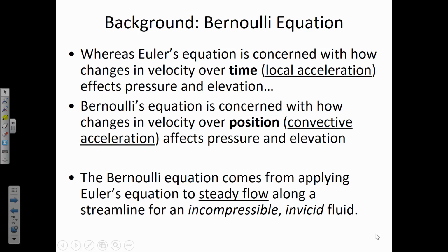Now, some fluids have a low viscosity, like gases, for instance, have a relatively low viscosity. Liquids, their viscosity is higher. So it's kind of interesting that when we've got a fluid that satisfies the incompressible assumption, like a liquid, water is relatively incompressible, but it's bad at being inviscid. But then gases are good at being inviscid since they have a relatively low viscosity, but they sort of fail the incompressible test. So, I mean, you can never satisfy Bernoulli's equation, right? But the thing is that it's good enough in a lot of cases.